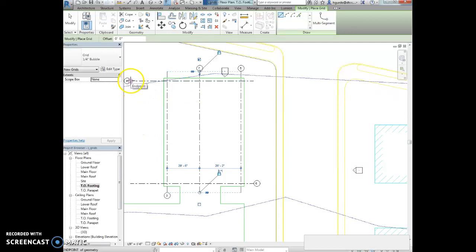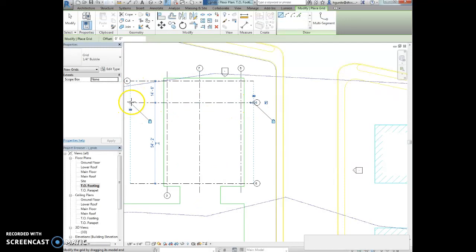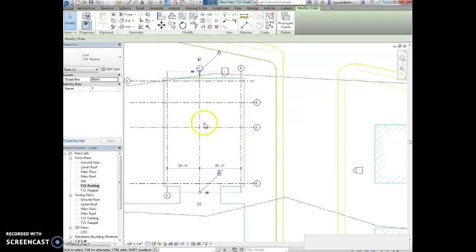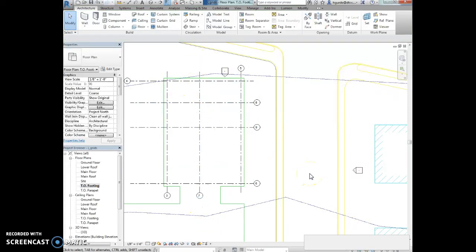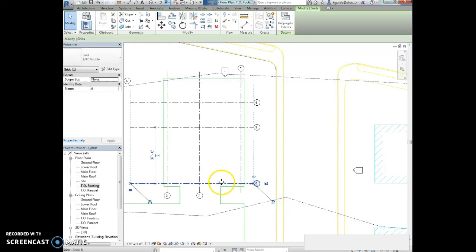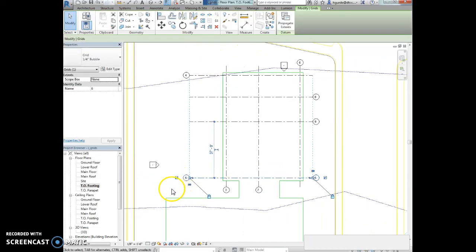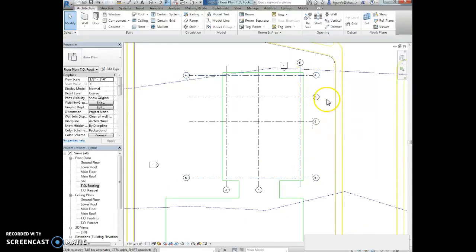I'm going to come down. It looks like I need a vertical grid over here, and then I also need a vertical grid over here. Okay, again, make sure you're using those little blue lines that come up to make sure everything's aligned. Okay, with 7, we want the bubble down here, so we're going to check this box, uncheck this box. Oh, and with 6, I just noticed we wanted 6 on both sides, so I'm going to check 6 over there, and also with 4. Sorry about that. Okay, so good. So now I look like I have the figure. My figure looks similar to the figure in the textbook.